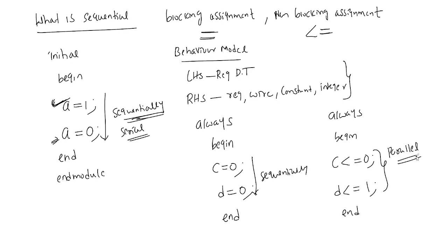Sir, in between two non-blocking, if I make a blocking statement? Basically, blocking assignments are used for designing combinational circuits, and non-blocking assignments are used for designing sequential circuits.